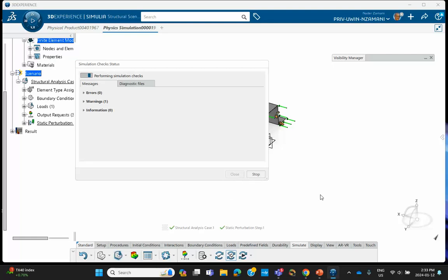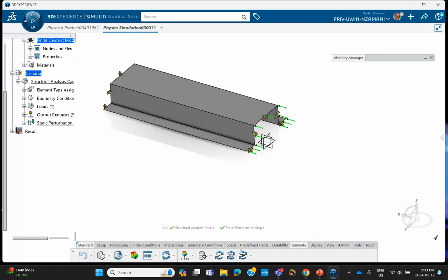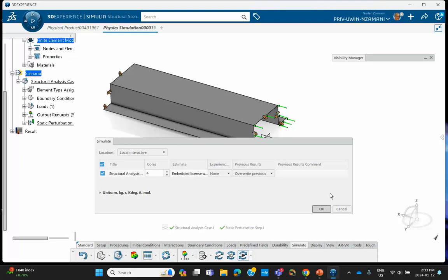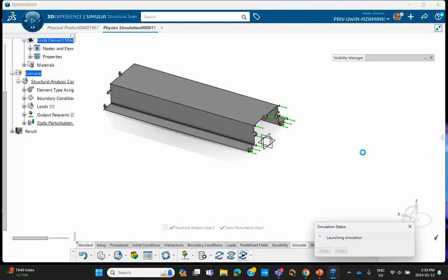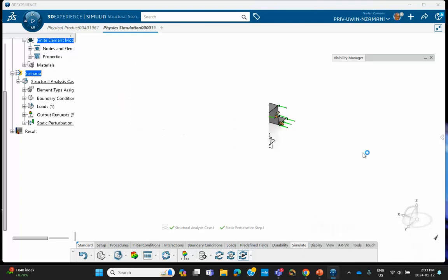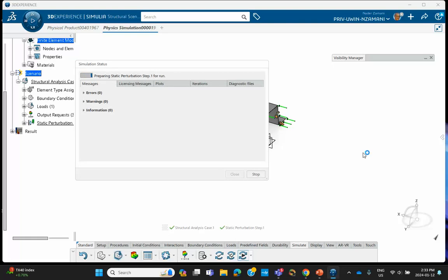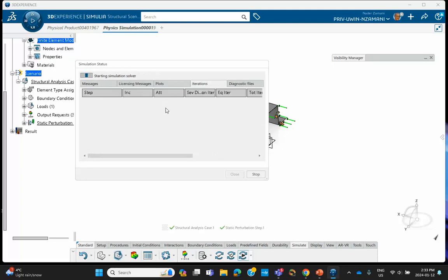And when we check our stress in the middle section of that folded sheet metal, we should come up with something close to that number that we have from the indicated paper. Okay, now we're going to run it. So linear analysis is going to go very quickly. There are no iterations here, so really it's going to be one increment.